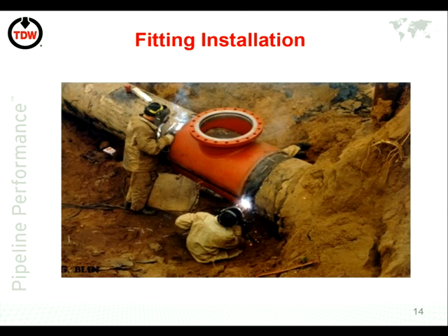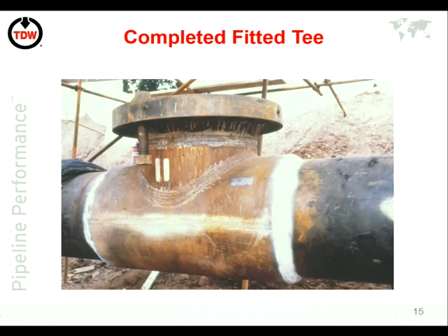Because the welding itself is to follow obviously strict welding codes. The welders who do this have to be certified specifically for doing this operation. And after the welding's taken place, there is a full NDT that goes on here to ensure that that weld is correct. As I mentioned, that has to remain on the pipeline, and the integrity of the pipeline will be affected by the integrity of that fitting.